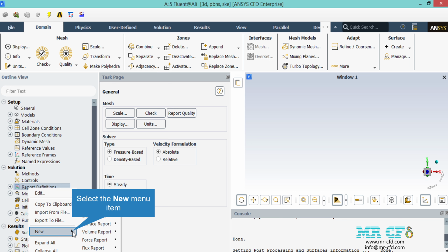If yes, it may be a sign that your simulation has reached convergence, but the residuals must be checked as well. For example, in this project, a pressure drop report alongside the porous zone is defined, and when the simulation is running, you may see how the pressure drops when the flow passes the porous zone.